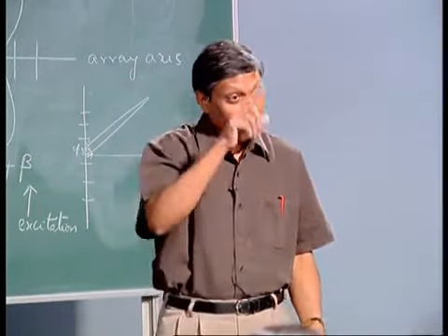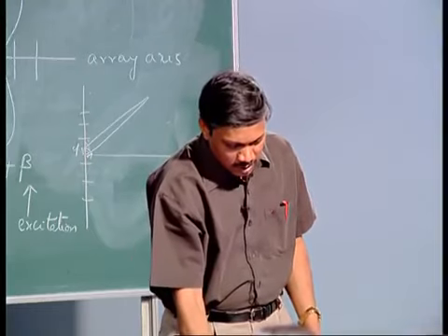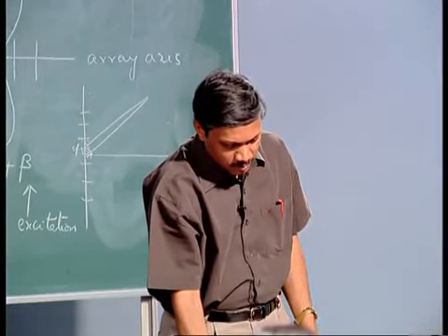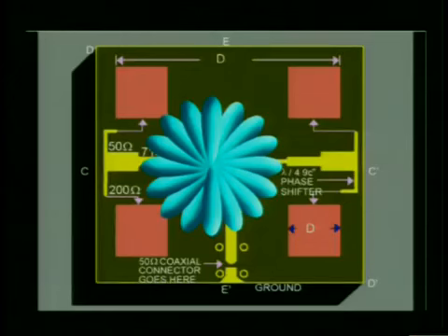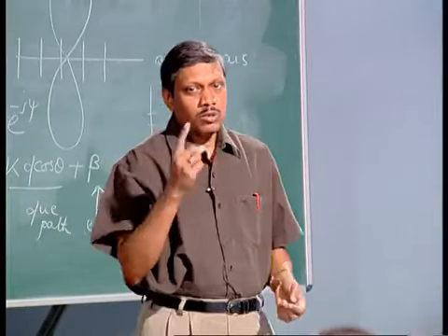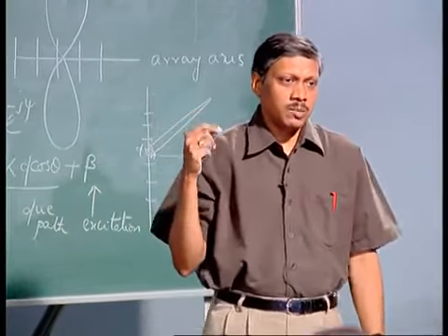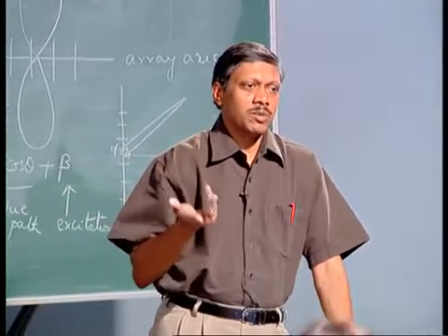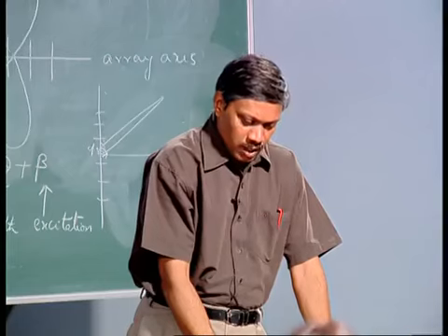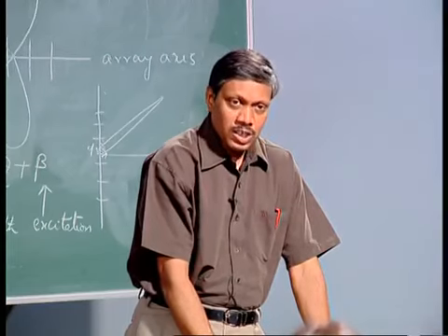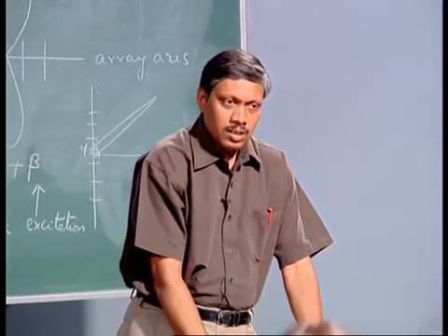The previous slide, if you see, this is a situation of grating lobes, where almost all are of equal amplitude. All right. This is already explained: if you have a lambda or 2 lambda type of separation, you will have this type of problem. So, to avoid the grating lobes, you must keep your spacing between the elements less than lambda.